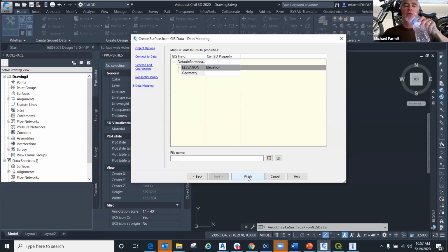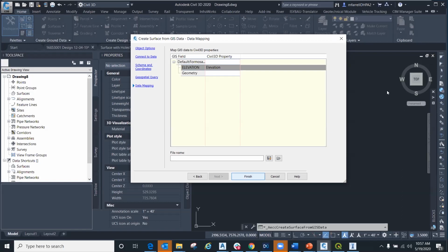And so instead of adding all of those to the surface as either contours or break lines, for me it made sense to just do a map export to shapefile. I just recently had a project for this exact same issue. I got a drawing from a client, and it only had 3D contours in the file. So I wound up creating contours in my surface using those polylines, and this probably would have been a much more efficient way.